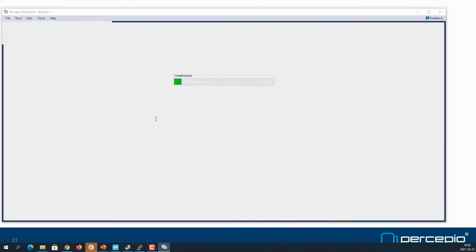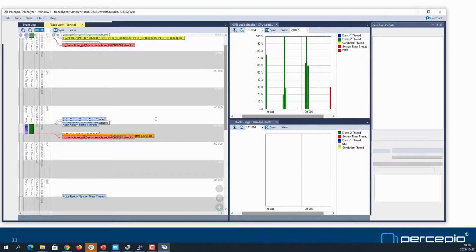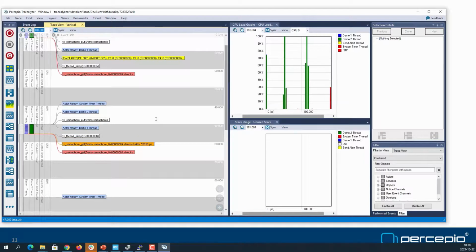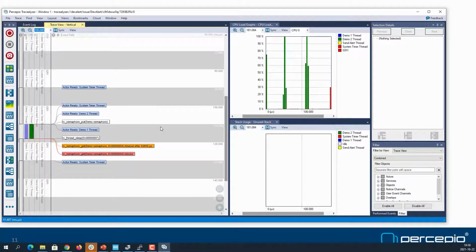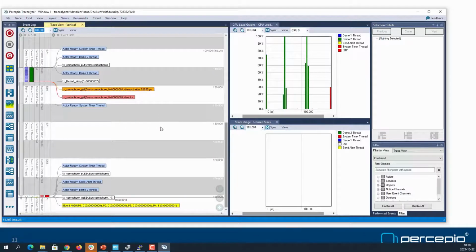So it's downloading and just opening the trace like that. So that is it. As you can see here, we have the trace. It looks similar to the example I've showed you before, but this trace is much shorter because it's just a snapshot buffer. It's just a few kilobytes. So you just see the last roughly 200 or 180 milliseconds here, what was going on in the application.